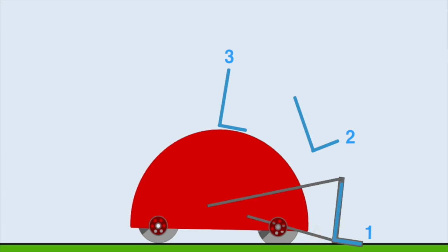We would like the pickup mechanism to be tilted slightly downward as you drive into the balls, and then in position 2 we want it to be tilted back so the balls don't fall out, and then in position 3, we would like it to rotate clockwise and tilt back the other way to dump the balls into the hopper. So the question is, how do we determine the length of the links and the location of the pivot point so we get this type of motion?